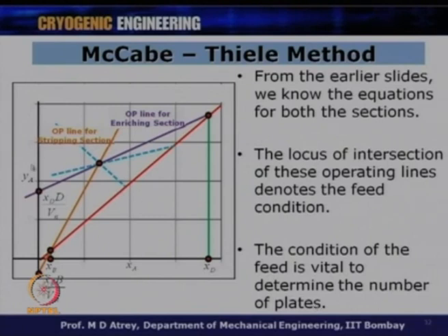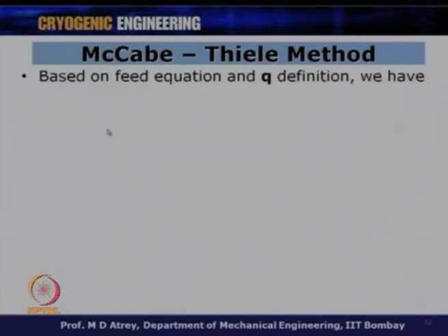So, what is this locus? This locus could be like this, the feed line could be like this, or anywhere in whatever direction. And this is very important to understand how many plates are going to be there in the enriching section or in the stripping section. This plays a very vital role. And how does it? So, let us see.